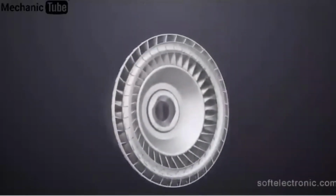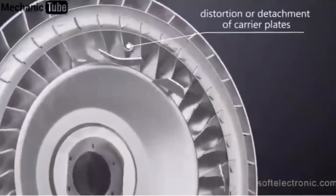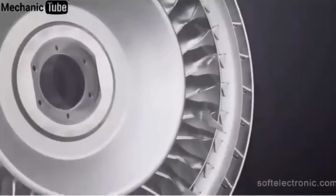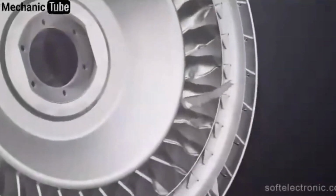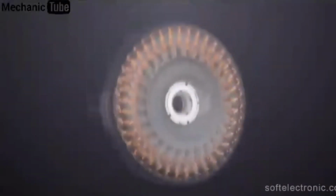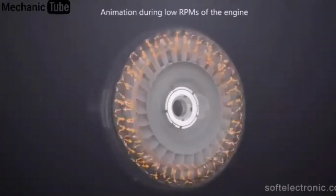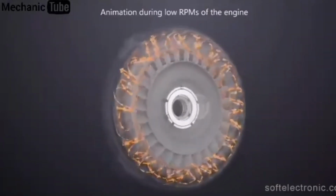Under such conditions, a turbine blade or the pump may break, which begins to circulate freely in the fluid flow. This can seriously damage the components of the torque converter. If there's a problem with the one-way stator bearing, this can have a serious negative effect on the flow control between the pump and the turbine.